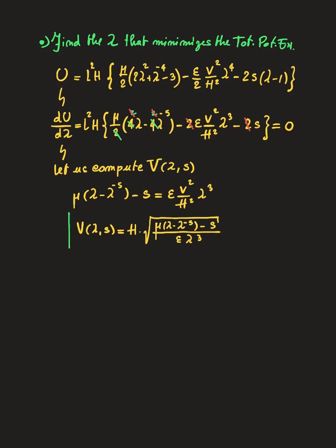We have been able to understand how the stretch, the voltage, and the applied loading are related in the membrane. Now, before checking if this corresponds to what we observe in the experiments, I want to plot this function. For simplicity, I just put mu equal to 1 and epsilon equal to 1. And I've plotted this curve for various values of s, okay? So s is equal to 0, 1, 2, 3, and so on. So this is what I observe.